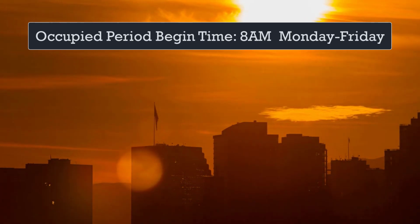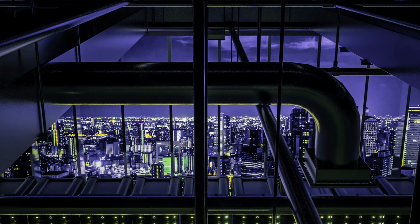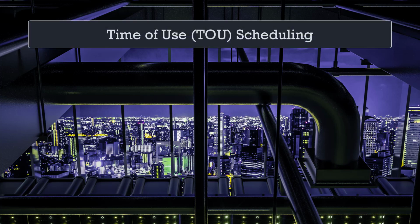Monday through Friday. During the building's unoccupied period, typically 118 hours per week during nights and weekends, when HVAC services are not compelled by the lease, BAS controls automatically shut down HVAC equipment to reduce energy consumption. This is known as time of use scheduling, a practice much like programming a residential smart thermostat. Time of use scheduling allows indoor temperatures to drift outside the building's occupied period temperature comfort range.